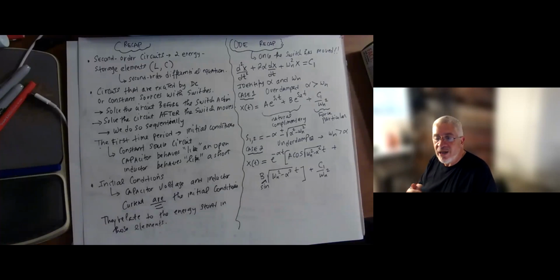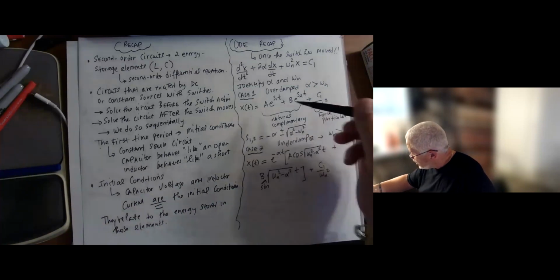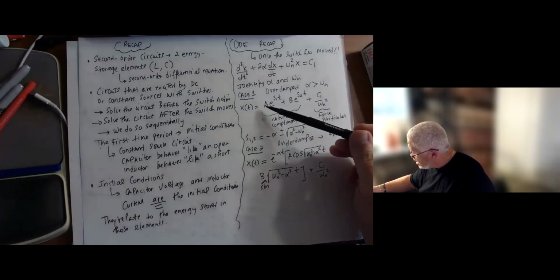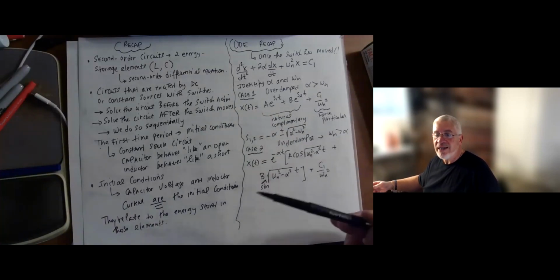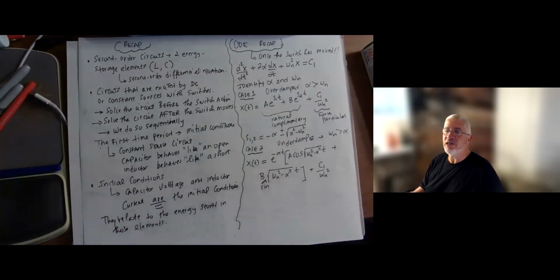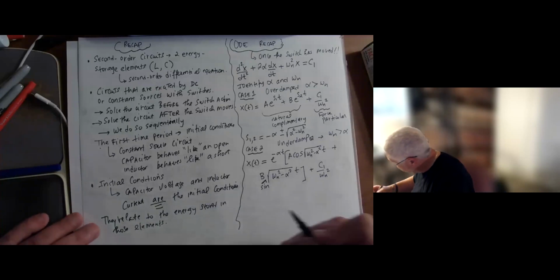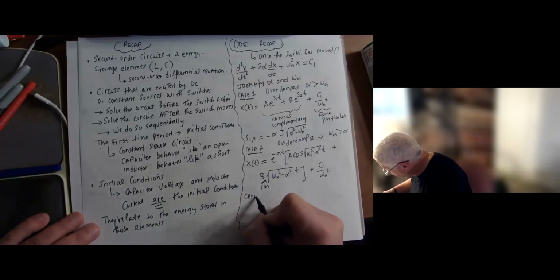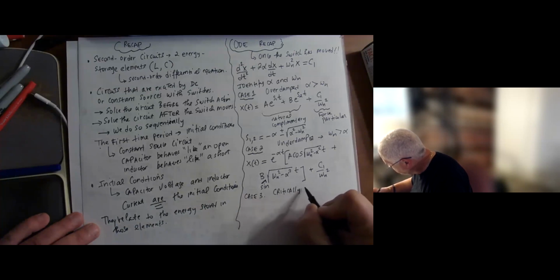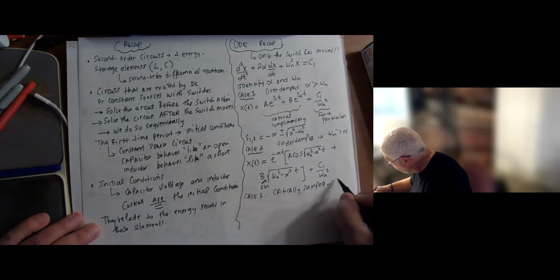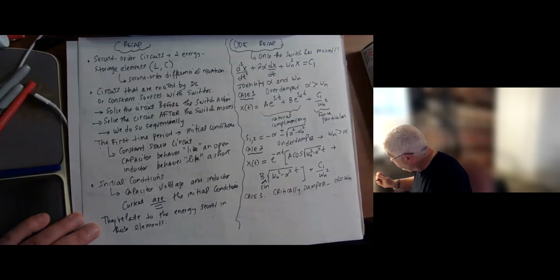These are the two most important cases. What you have here is what I call the general solution, general because constants A and B are not determined yet in both cases. These are determined via the initial conditions. Finally, case three, which is a much less interesting case, is called the critically damped case. It's the double root, alpha equal to omega n.